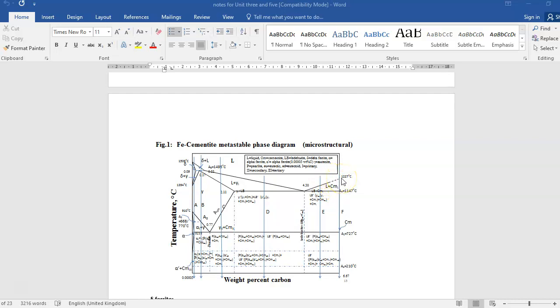This is because of the sublimation of carbon. Sublimation means that when you give heat to carbon, rather than going from solid to liquid, it goes directly from solid to gaseous state. That is the reason we do not have the final melting point. Second, carbon is the element which makes the material more brittle, because the more the carbon, the more the stress, the more the strength, and the more the cementite, which is a hard phase.